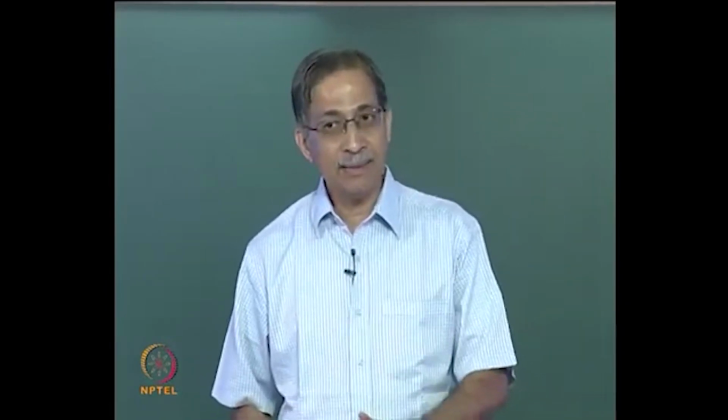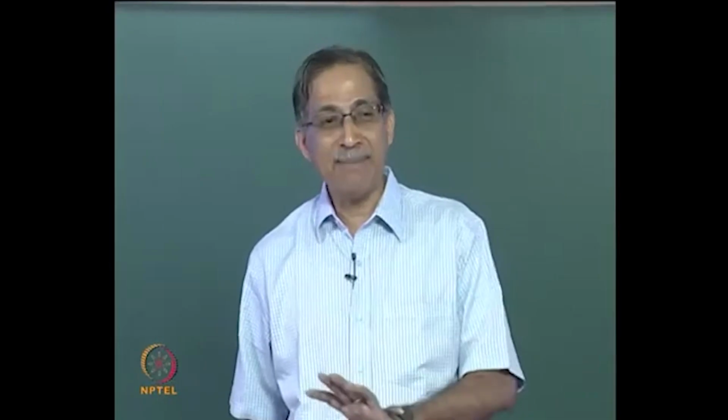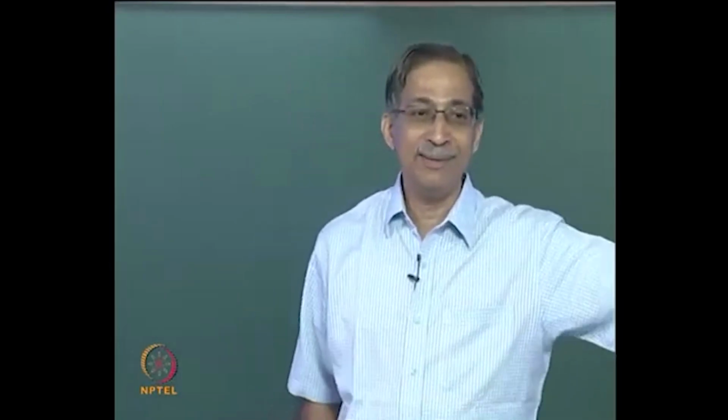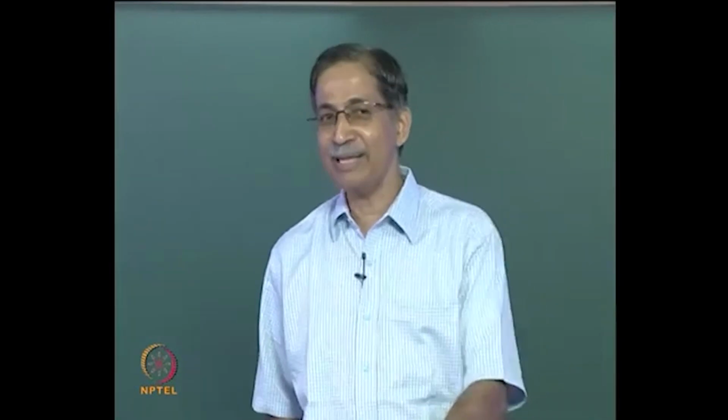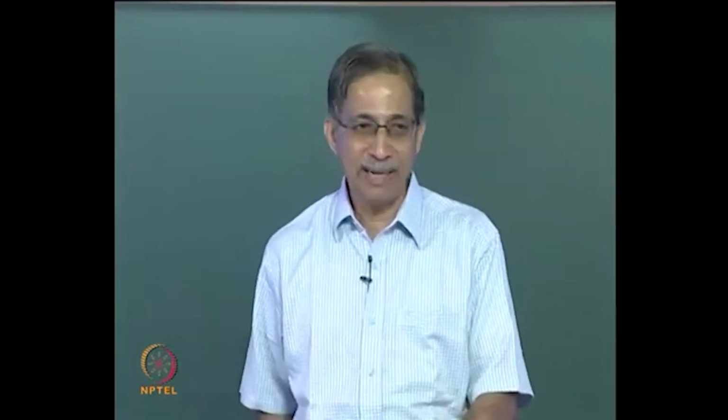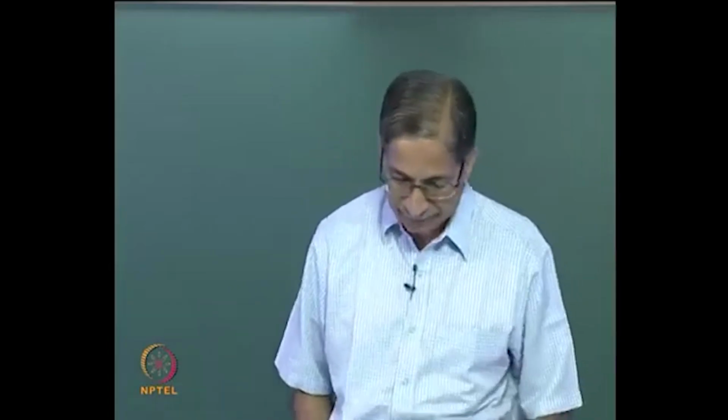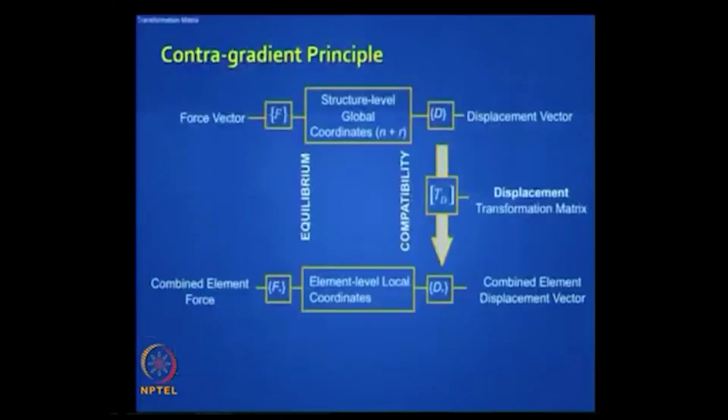Now when you do the reduced element stiffness method and the flexibility method, you can't program it as blindly as you could the conventional stiffness method, because you are trying to take a shortcut. You have to apply your brain a little bit, especially in generating the fixed end force vector, which we will see later. So you can do this. Now let us look at the contragradient principle.